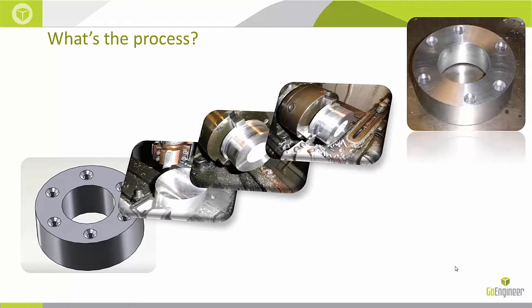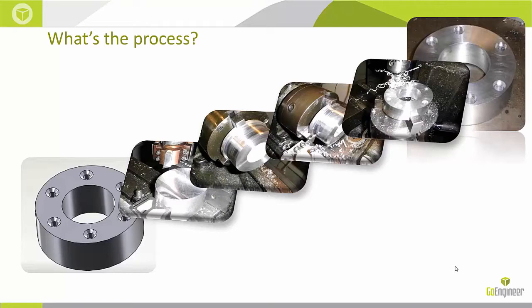But as I'm creating the model, I'm using features to define the individual manufacturing practices that we're going to need to use in order to create this geometry. So we might start off with saw cutting a piece of aluminum bar stock, and then we want to face that off, get a good true side on that, and then take that to a lathe and start turning down the ODs and IDs. We'll finish that up with some milling and drilling processes in order to create our geometry. And so those are the steps in the physical world in order to create that model.